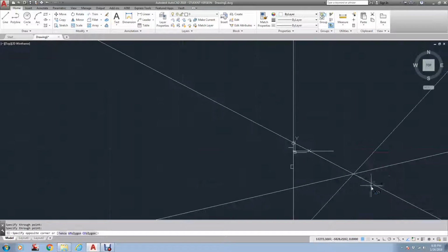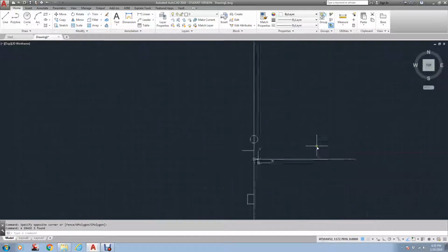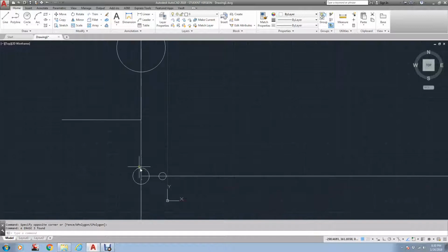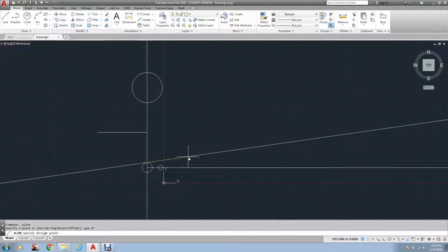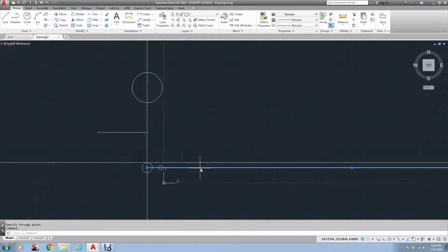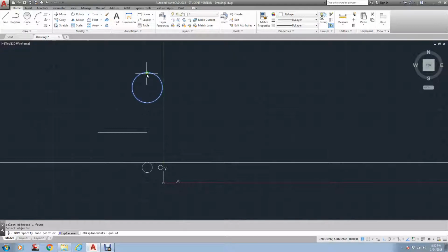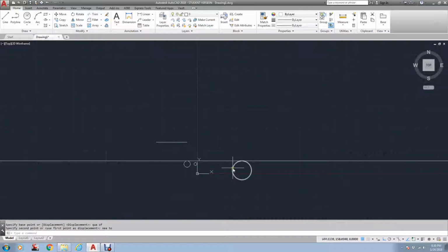If I wanted everything to line up with the top of my circle, I could just go to construction line here, type in QUA for the quadrant, turn on my ortho, and now I could have everything line up if I wanted to move this circle. I could go quadrant and then just type NEA for near. If you haven't watched the OSNAP video, I would say stop and do that, because I'm using quite a bit of object snaps. But again, this is just that guide.